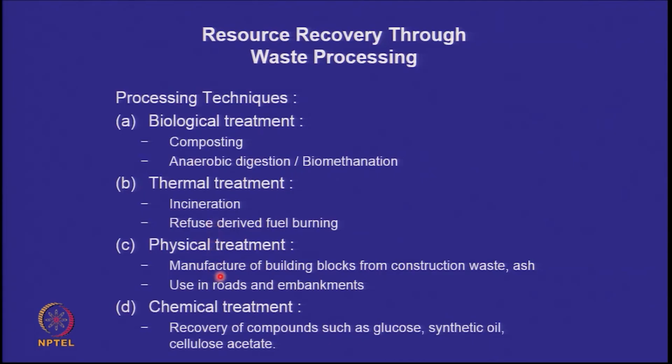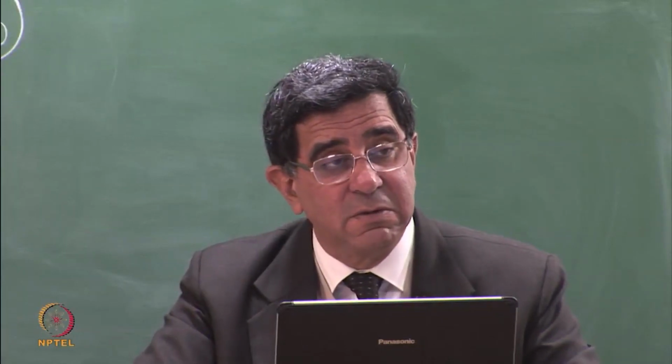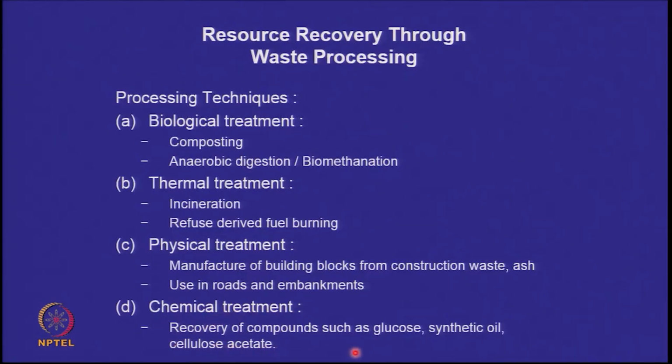If you have ash, if you have construction and demolition waste, can you use it for building blocks? Can you use the ash in roads and embankments? If it's not hazardous, instead of using earth, which you will dig up from some farmer's place, can you do that? And you can also do some chemical treatment for recovery of compounds. So all these resource recovery processes require more investments in terms of giving energy and materials to make this happen. But in the end, the recoverables do outweigh the investments which are made.